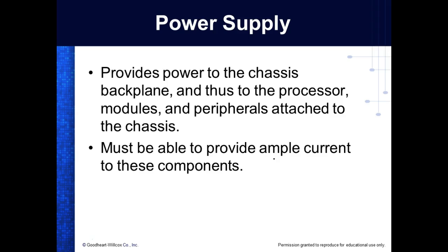And usually in PLCs it's 24 volts, plus 24 volts. Now it doesn't mean you can't switch 120 volts. It's just that the electronics runs off what? 24 volts.